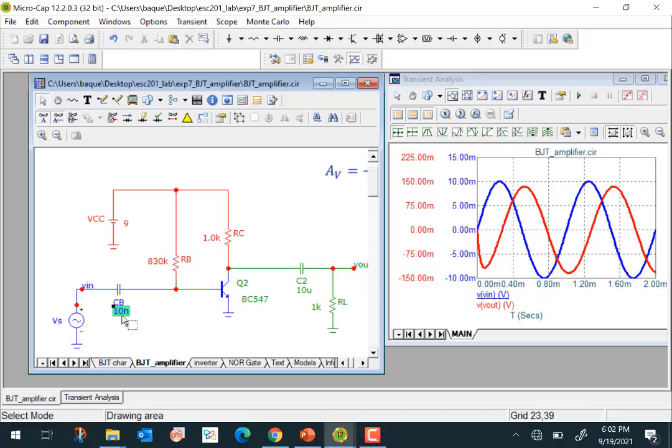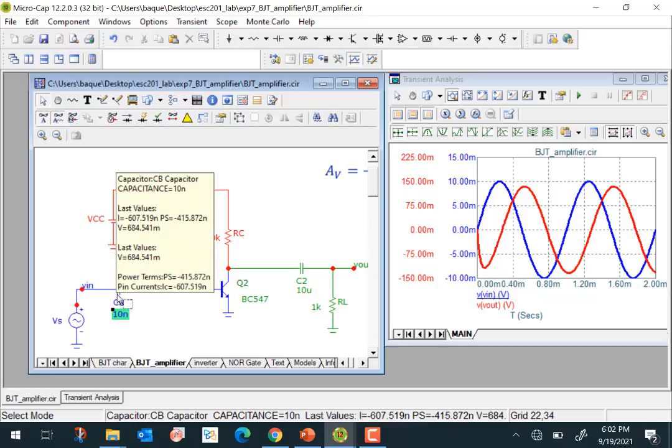And the basic reason is that at that particular frequency, a lot of the voltage that you apply is dropping across the capacitor here and is not going into the amplifier at 1 kilohertz. You can calculate the impedance here, and you'll see the impedance is sufficiently high. So the capacitor doesn't act like a short here.